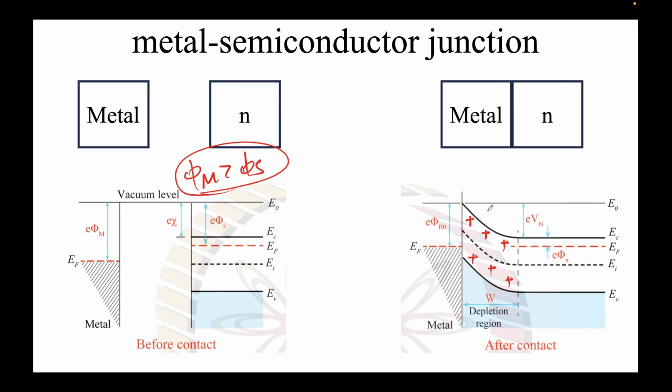So this assumption is again valid over here. We are borrowing the same depletion approximation. On the extreme right, the behavior still retains its pure n-type characteristic, the bulk characteristics, right? This is just like the bulk, just like we had the quasi-neutral region in the p-n junction. A very similar principle we are using here, right?